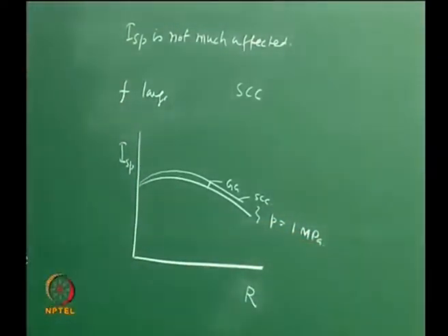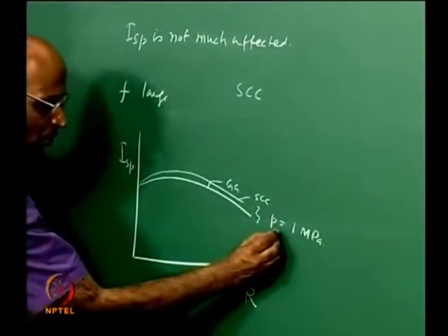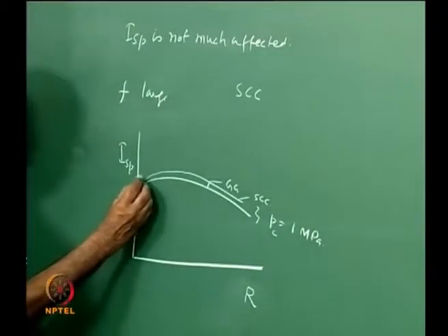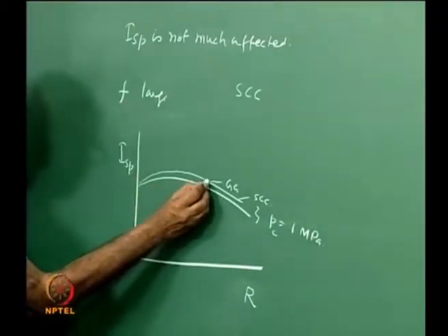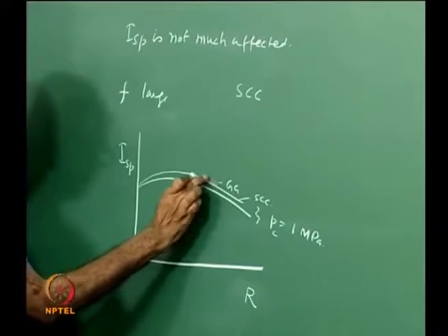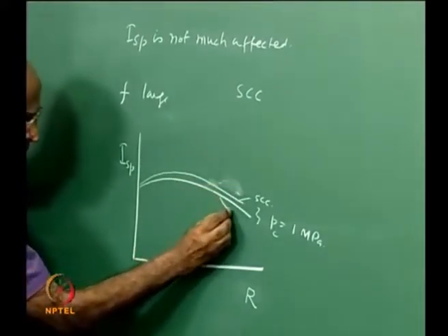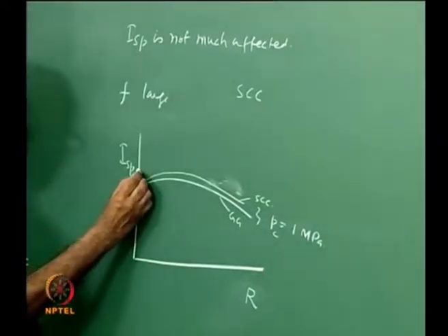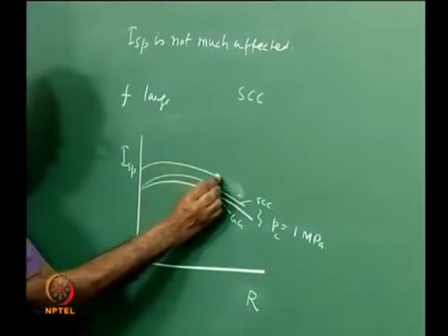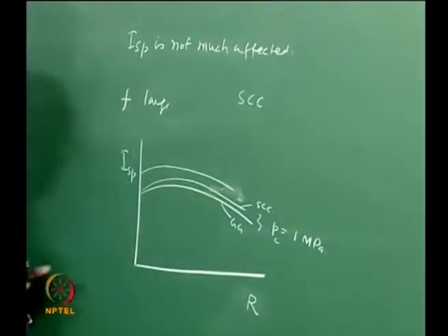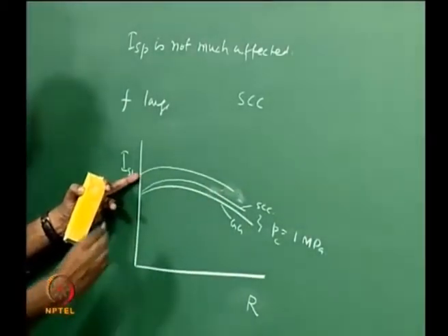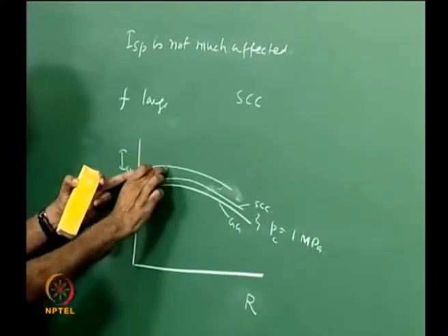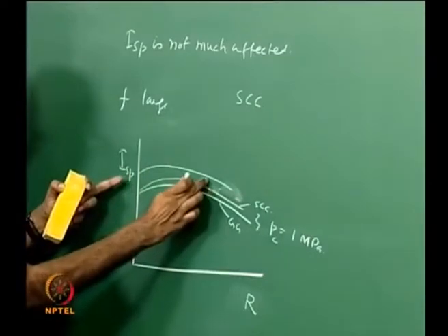But now if I were to operate my engine at, let us say, 10 MPa, which is slightly higher pressure, in that case the GG cycle, let us keep the terminologies clear, GG cycle, will give slightly higher performance, but my stage combustion cycle is going to give me a performance which is very much higher, because this ISP came from pressure even though the F dropped.